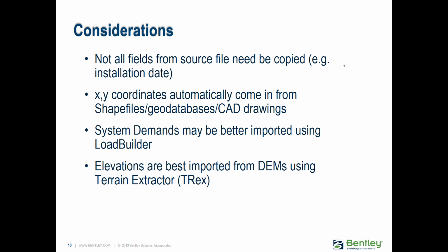So if you can imagine a curved pipe, where there's 2 junctions, one at each endpoint, but the pipe has a curve to it. If your data source file is a shapefile and it has that spatial information built into it, when you import it, you'll end up with a curved looking pipe, because it will import all those little vertexes, the bends in the pipe.